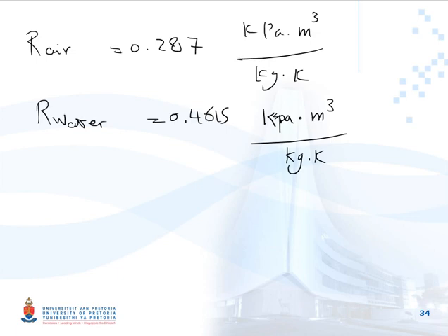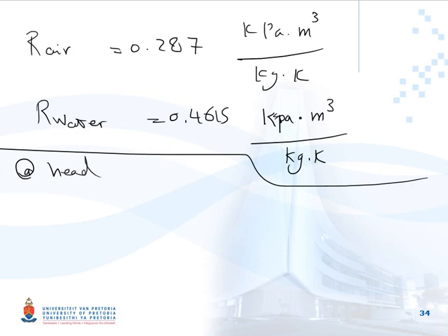When the head is dry, because it's saying there are two different conditions, so first we are assuming that the head is dry. Okay, so when the head is dry, heat transfer from the head is just by forced convection and radiation only. Why forced convection? Because we have a wind and it's very strong.